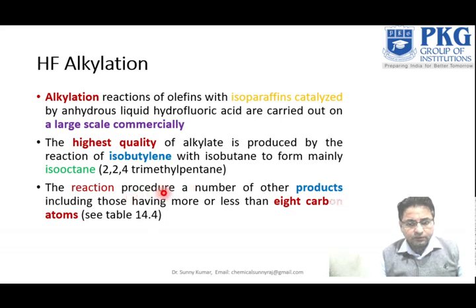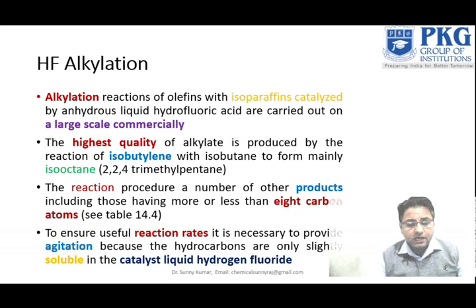In the reaction, a number of other products are formed, including those having more or less than 8 carbon atoms, that we'll see in table 14.4 in the next slide. To ensure useful reaction rates, it is necessary to provide agitation, because the hydrocarbons are only slightly soluble in the catalyst, liquid hydrogen fluoride.